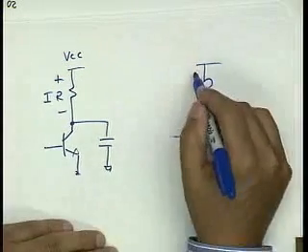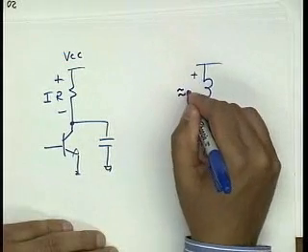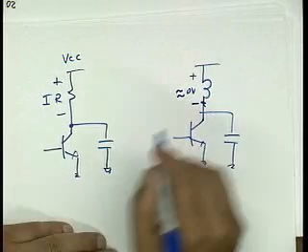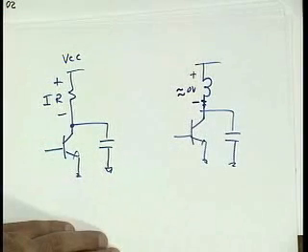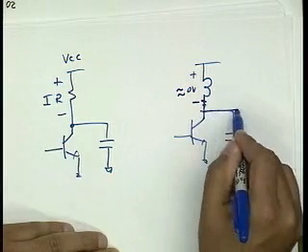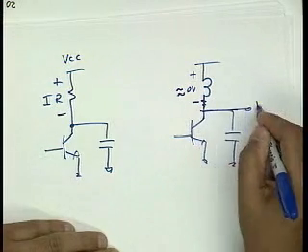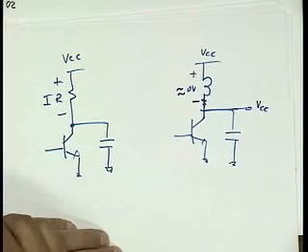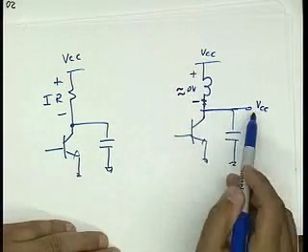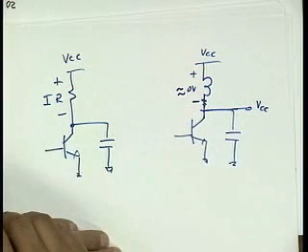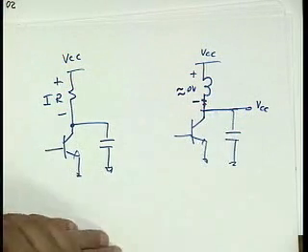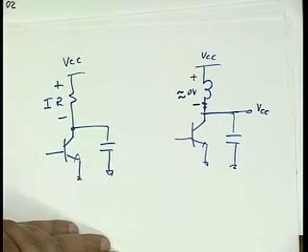Over here, though, the DC voltage is approximately 0 volts, right? Because there's a very small resistance in series with this, the winding resistance. And so the DC operating point at the collector here is actually VCC. And no matter how much current I put through here, this DC operating point does not move. So this thing always operates with the full available power supply voltage.